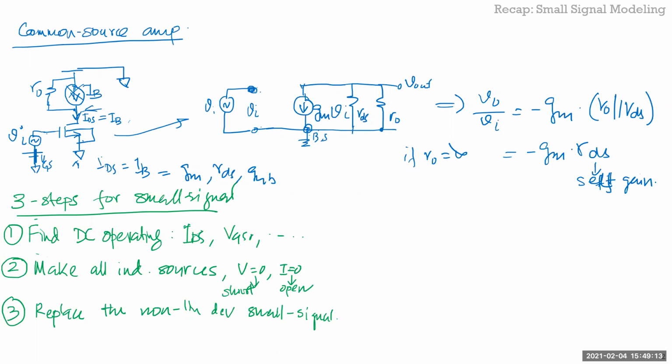So we'll see how to get the FT of the technology from the high frequency model once you have the cap, because without the cap, obviously you don't have any frequency response. And that we'll probably see when we start doing the frequency response of circuits. Till then, it'll be all low frequency analysis, okay? So this is sometimes called the self gain.